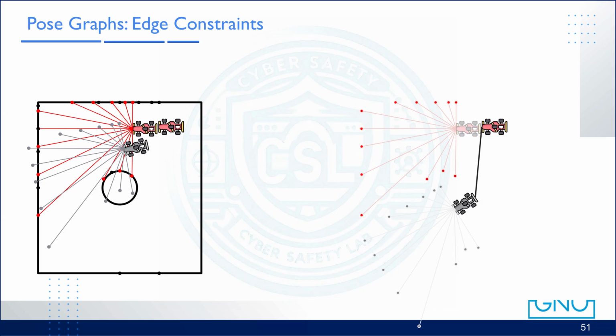If the odometry measurement is highly reliable, the spring becomes very stiff. It strongly resists any attempt to move the two poses apart from the position predicted by odometry. Even small deviations will generate a strong corrective force. On the other hand, if we are not very confident in the odometry, the spring becomes soft. It allows the poses to shift more freely and bend into a configuration that better matches the rest of the constraints in the graph. This spring-based interpretation explains why graph-based SLAM works so well.